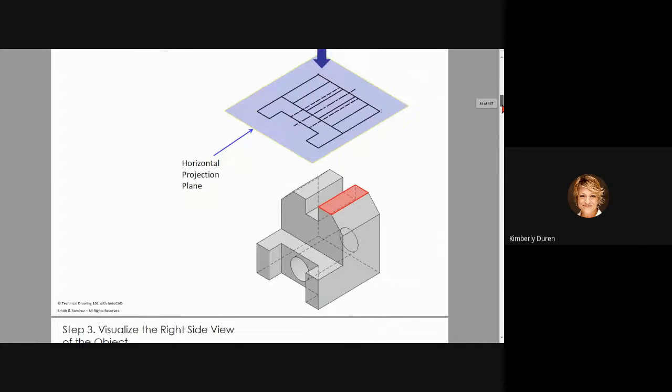We'll go through this one. From the top, I can touch these. And you see where with these hidden lines, this starts to get really confusing, right? So the visible lines, I know I can touch. Hidden lines, I can't. This is that hole that goes through, and I know it's a hole because this axial center line goes all the way through, and it goes beyond the circular element, so it goes outside. Hidden lines will never stop at geometry. Edges stop at geometry. Center lines go beyond geometry every time to let you know that that's not geometry.